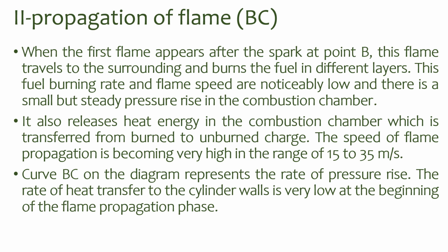The second stage is propagation of flame, which is represented by BC. This is the most important stage of the combustion in SI engine. When the first flame appears after the spark at point B, this flame travels to the surroundings and burns the fuel in different layers. The fuel burning rate and flame speed are noticeably low at the beginning, and there is a small but steady pressure rise in the combustion chamber.